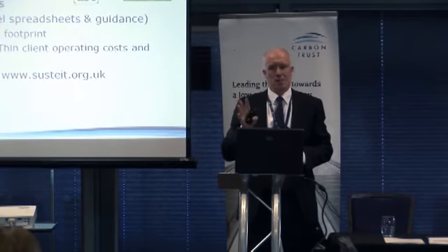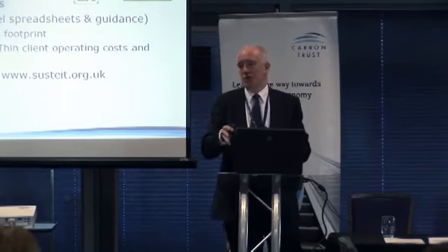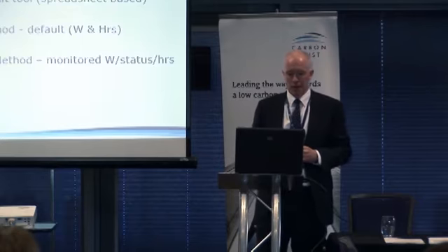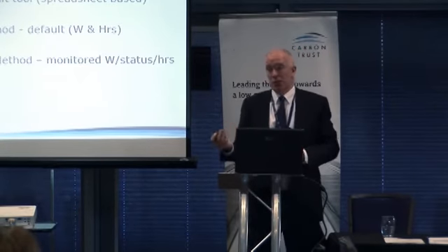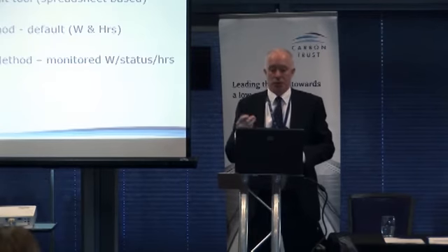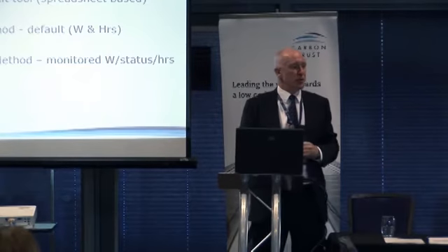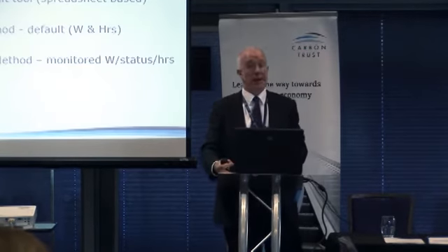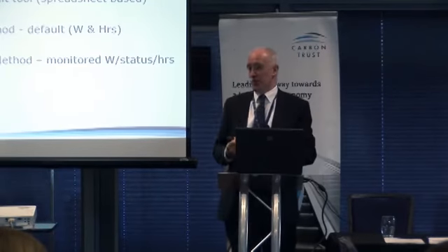I just want to cover that because as a simple spreadsheet tool, this is a very straightforward, simple auditing tool for IT, and so I think it's useful for everybody. The tool is a simple Excel spreadsheet and asks you to complete it by two methods. One is to look at all of the items of equipment, you put them into the spreadsheet tool, along with the wattage that each of those take, and that probably comes from the plate rating or from the specifications, and you multiply that by the hours of operation.